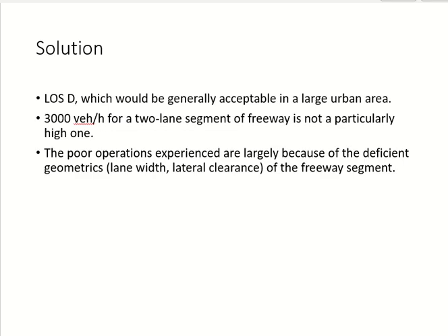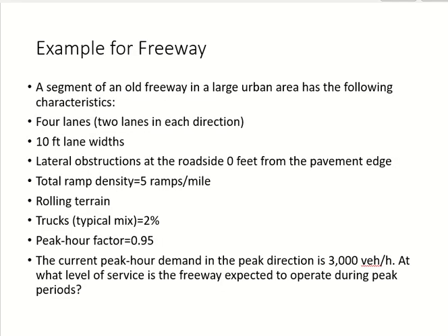It's not normal. Okay. The problem is, if you look at the question data, how much is the lane width? 10 feet. Okay. How much is the lateral clearance? 0. These are the minimum values. So your road is very narrow.